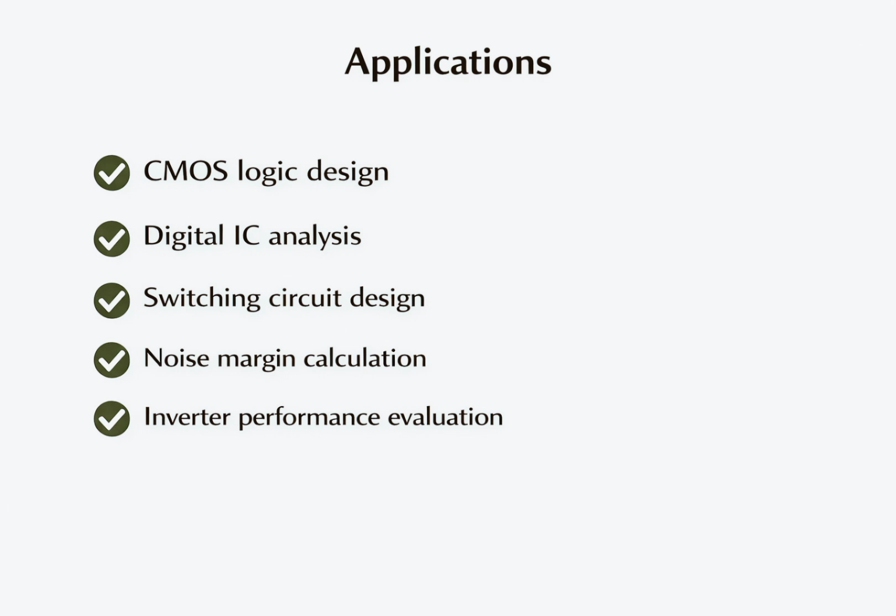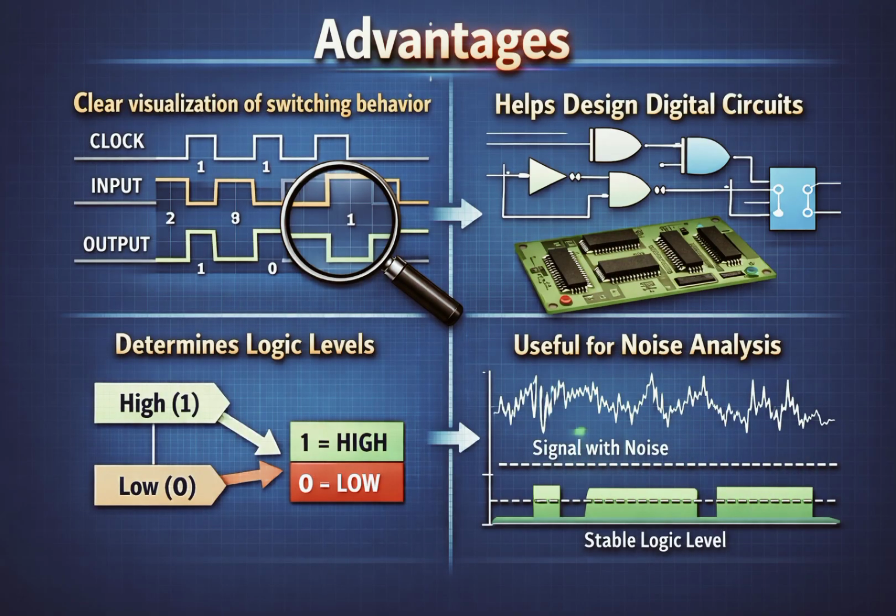Applications. Voltage transfer characteristic analysis is widely used in CMOS logic design to evaluate inverter performance. It is also applied in digital integrated circuit analysis, switching circuit design, noise margin calculation, and inverter optimization. Engineers use VTC curves to ensure proper logic levels and reliable operation of digital systems.